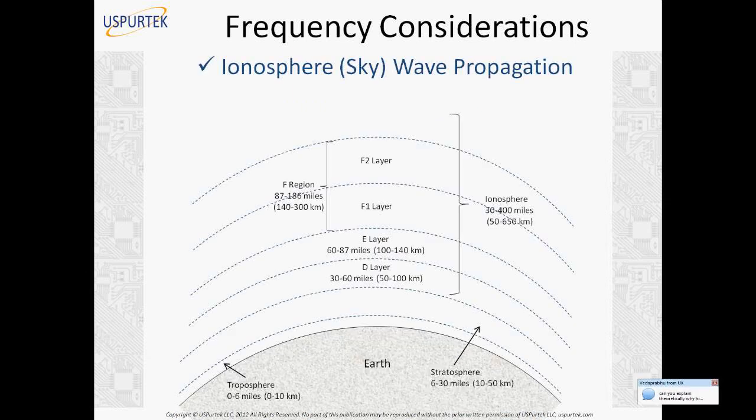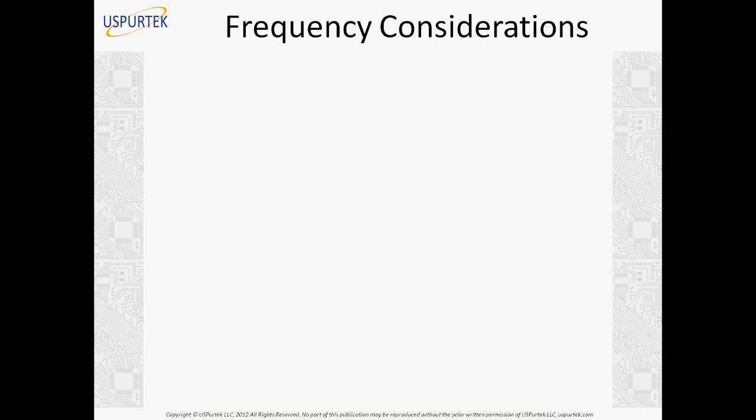Now let's go to ionosphere wave propagation. Well, okay, there is a question here: why are high frequencies low range? Well, when we go to later slides, we'll talk about the free space power loss. So with frequency, the power decreases actually. If you have higher frequency, lower power. There is a direct mathematical relationship. This is a property of electromagnetic waves. So that is how we get that.